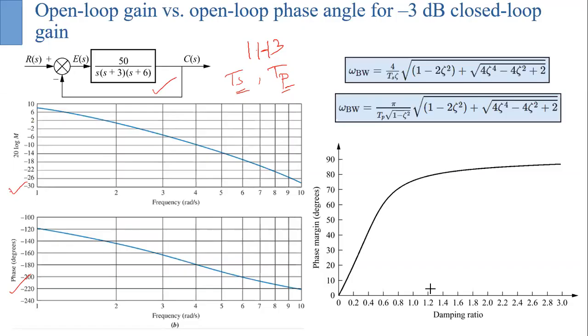Just as in the previous figure, we have to see whether we can figure out the minus 3 dB line. The magnitude is between minus 6 and minus 7.5, somewhere here, so in between here you have to find the point that gives you that, and then you have to verify the phase.